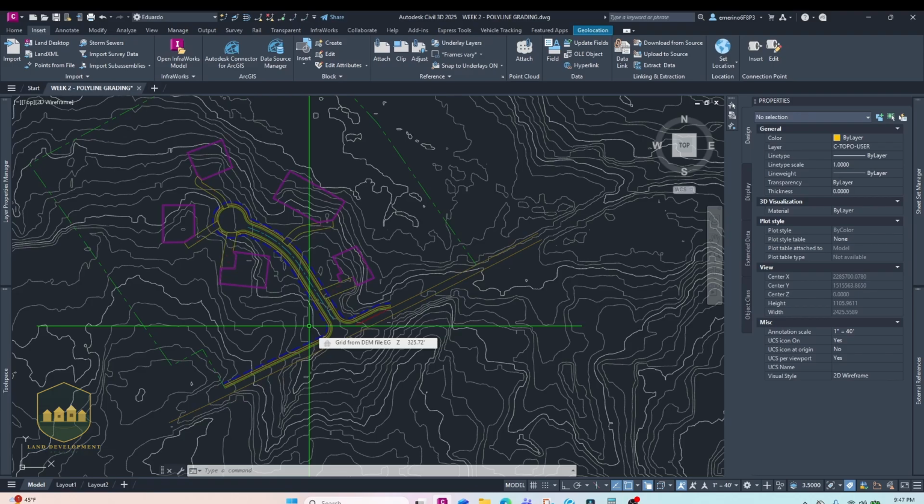They make mistakes all the time. They don't tie into the existing ground perfectly. They have floating contours, the boundaries cutting it off, the cross sections, sometimes it's messed up. I've seen plenty of times that feature lines are going from 2% to 1,000% to negative 1,000% back to 2%. And possibly the surface won't show it, but nevertheless, the surface is still wrong. And it's your job to make sure that the surface is right.